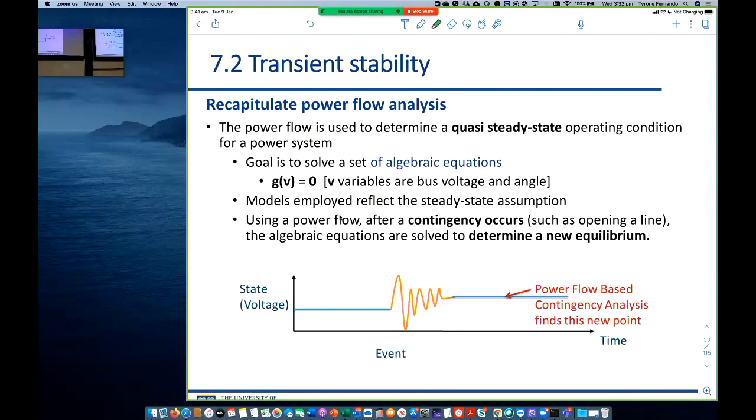Now, if the load condition then changes at a particular bus bar, the voltage at bus bars will change. It will move to a different location, like as you see on the right. And in between, the voltages at various nodes on the network will go through a transient. It will change, like oscillate a little bit as shown there, and will reach a new operating point if the system is stable, right? And we will talk about stability.